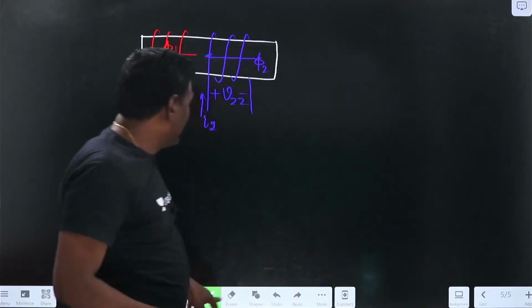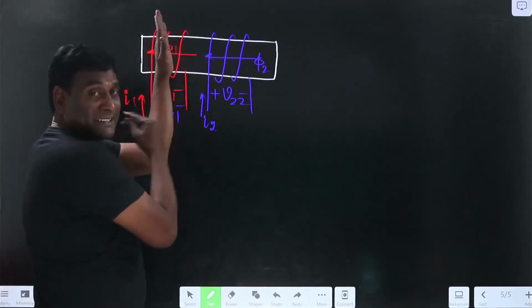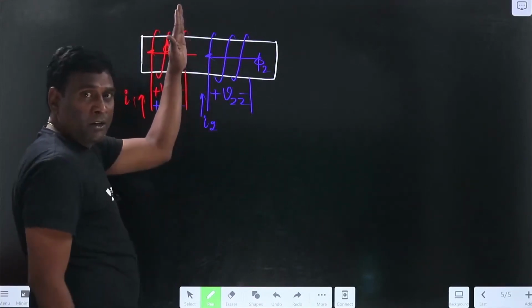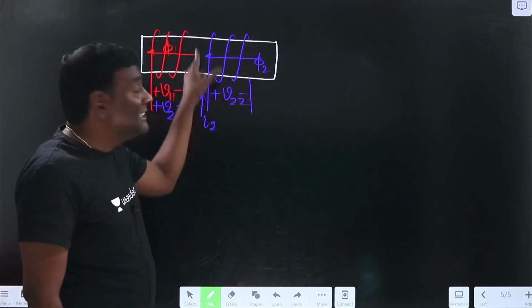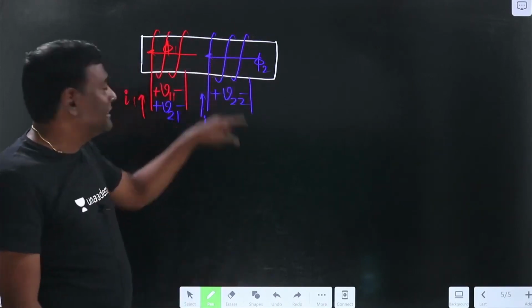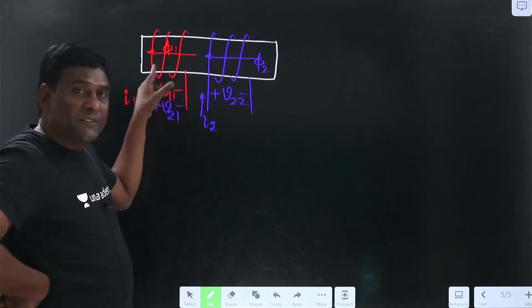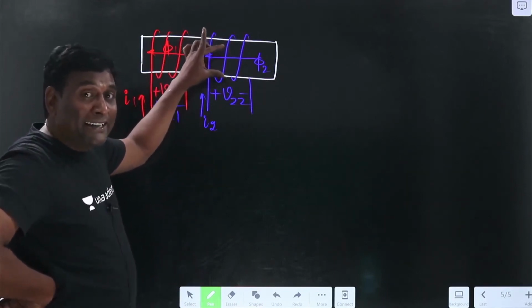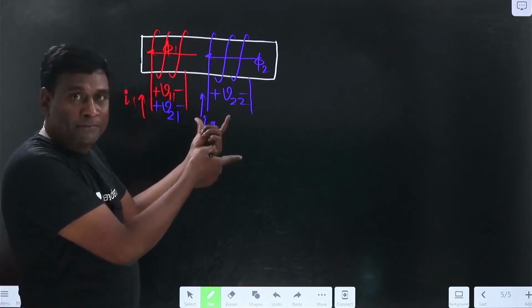Now if I think of red, when red is not there, then plus minus induced voltage will be induced depending upon the passive sign convention. Now when red is there, because of phi 1, net flux interacting with this coil is increased or not? Yes, because they are in the same aiding direction. Now because of existence of phi 1, net magnitude of flux is increased, meaning that net induced voltage across this should be increased because of phi 1.